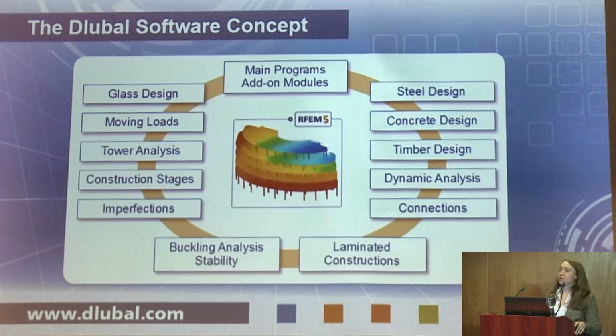As I said, RFEM is one of the main programs. It uses the finite element method for calculations. You can model the structure in this program. You can define loads and load combinations. You can do it manually or you can do it automatically. You will run calculations. As a result, you will gain the internal forces, deformations, support reactions, and stresses.